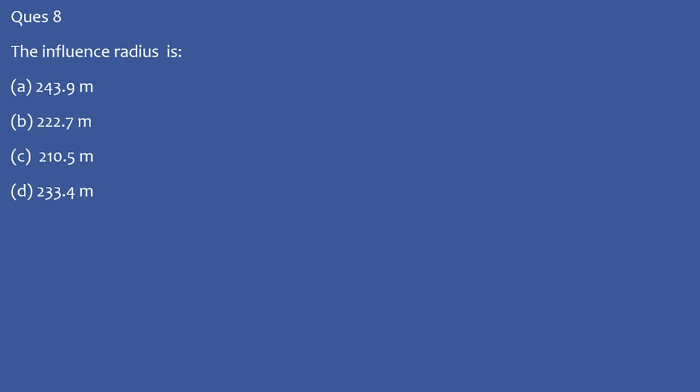So you need to evaluate the influence radius. Once you are extracting the water through the well, how much radius or how much area it is going to influence. The radius of that influence area you need to evaluate.